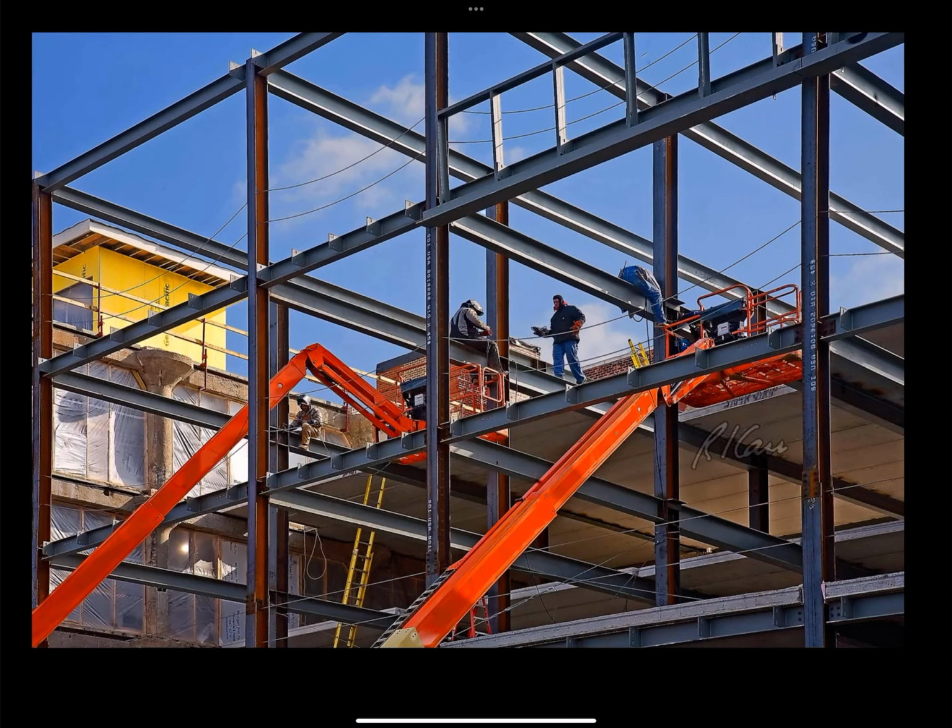So this shows a steel frame being erected on the building site. And what you can see here, or what I should explain, is that the columns are continuous and the beams are interrupted. And so the columns are continuous from ground to roof, and the beams come to the columns. The columns come to site in approximately 2-story high lengths, which are then spliced together on the building site.